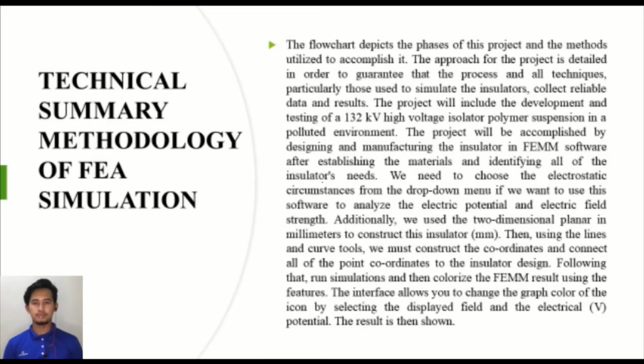Then, using the line and curve tools, we must construct the coordinates and connect all of the point coordinates to form the insulator design. Following that, run the simulation and then colorize the FEMM result using the features in the software.